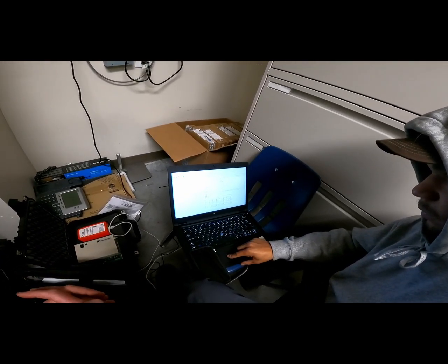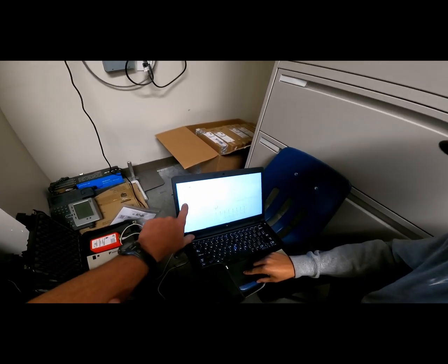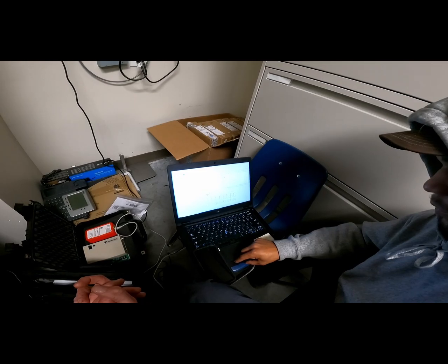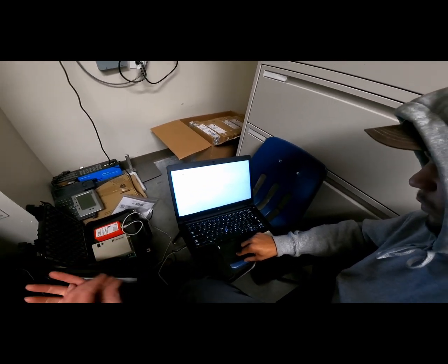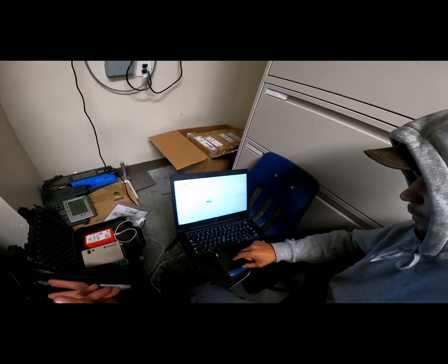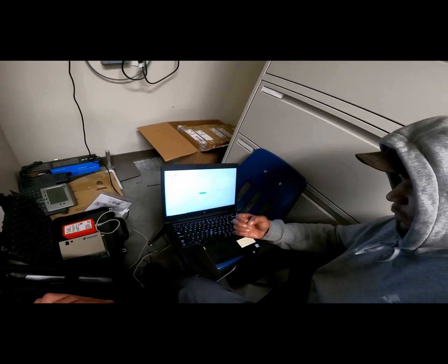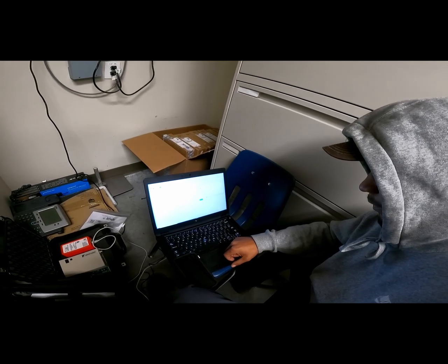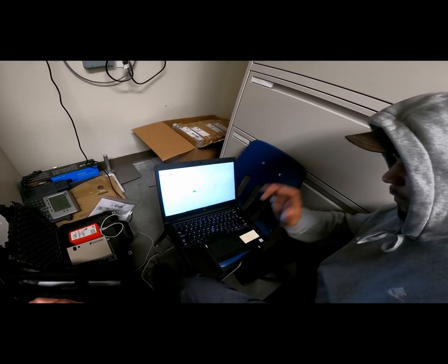So you're going to click monitor, then you're going to click the outdoor unit, the leader of the outdoor units that you're choosing, the OC, and then you go down to confirm. And what this is going to do is immediately start recording all the information that you see on this unit minute by minute, and that will show up in the upper right hand corner of the screen.